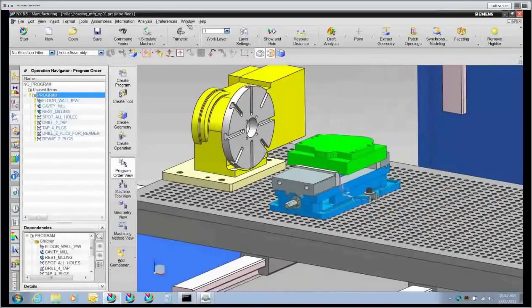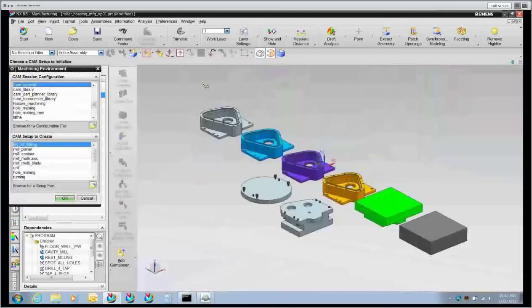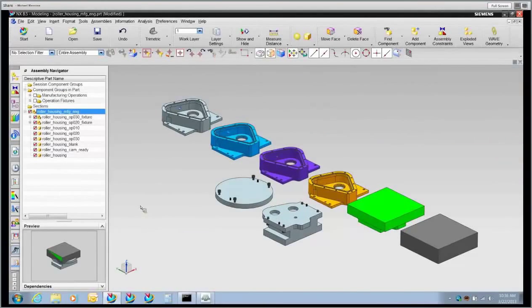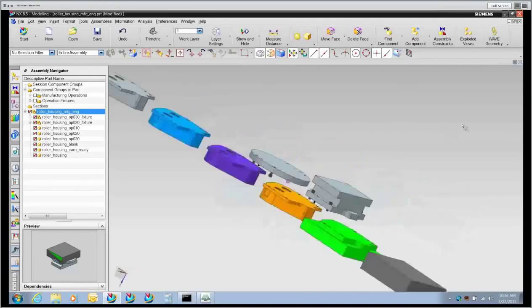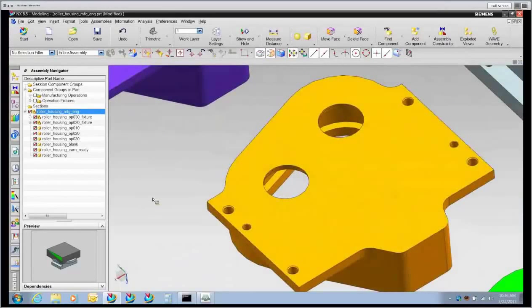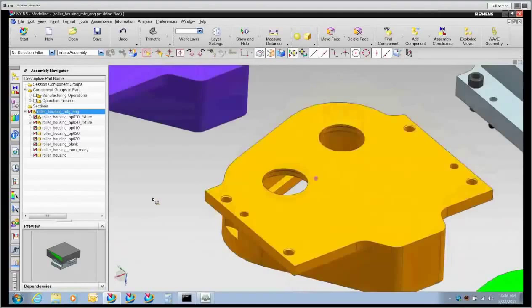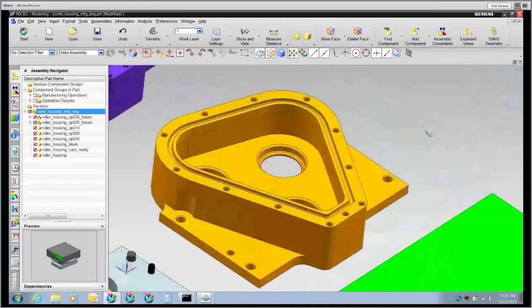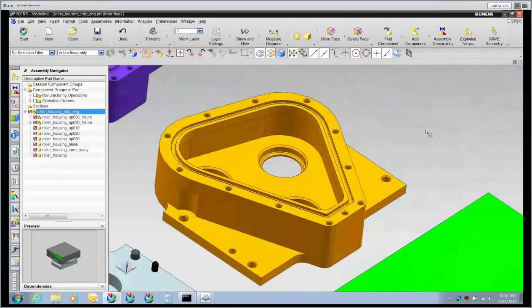I'm going to switch now back into my manufacturing engineering assembly. Now, the first time we ran this part file, we ran into a series of problems that we didn't foresee at the layout stage. On the back side of this operation 020, the large holes that go through, the drill put too much pressure on the part and we bulged out the back side when it created those two holes. Also, the bearing bores, because of all the heat generated in this operation, they change size as the part cooled down. So we have to separate those into its own operation.